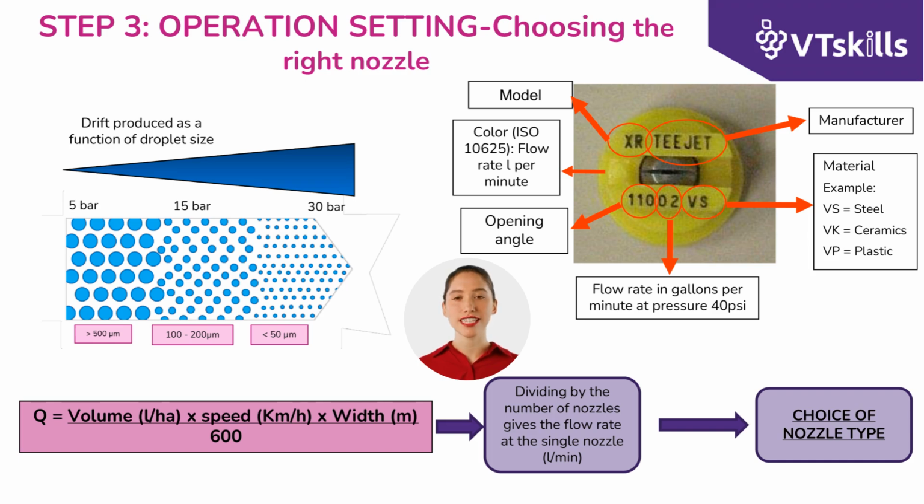The advantages are easy to convey to the foliage, but the disadvantages include the drift and limited versatility in terms of plant protection products that can be used. Medium-high volume machines exploit the pressure generated by a pump and nozzles in which the pressure drop and consequent atomization are generated. The advantages are the possibility of using different nozzles capable of generating a vast spectrum of droplet sizes that can be used on multiple targets.